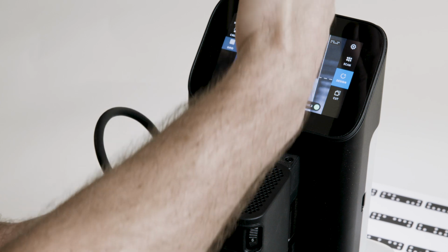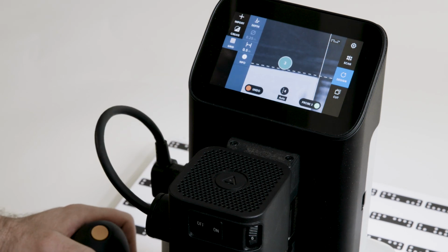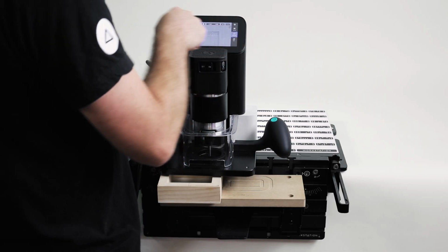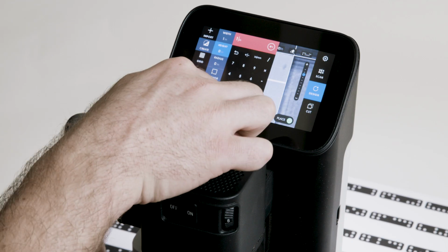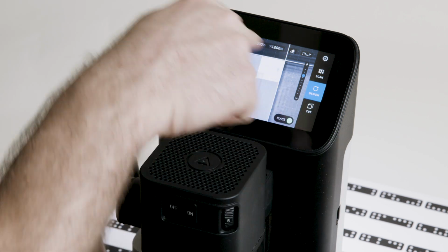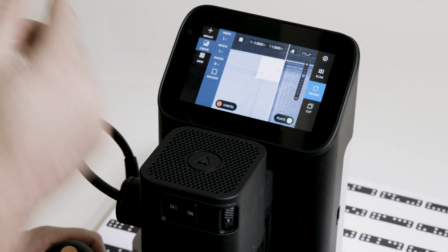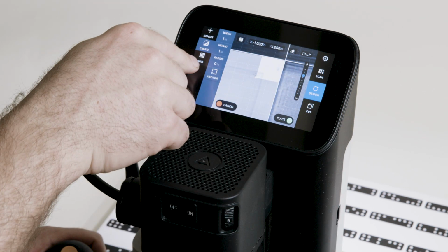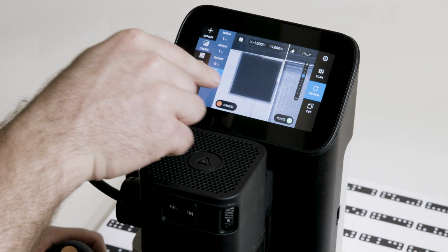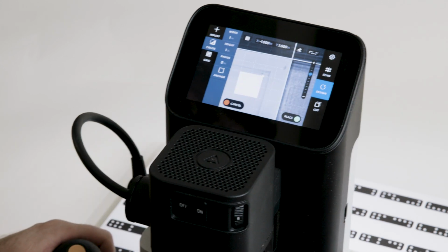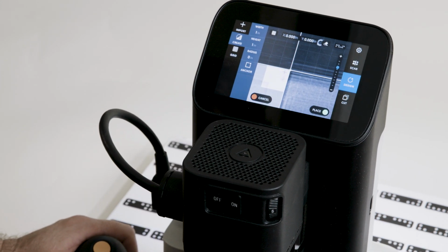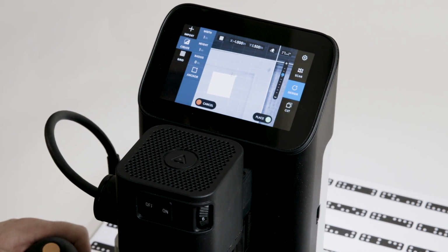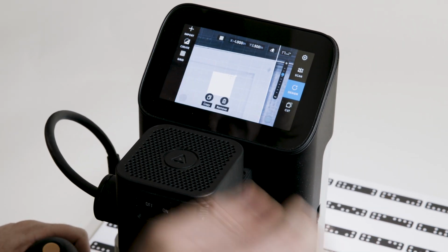So the first axis is technically X, and now I'm defining Y. So they're flipped 90 degrees, but it still enables me to place shapes, as we can see here, at very precise increments, very accurately aligned to the edge of my stock, and also oriented perfectly. I'm going to use the top right anchor point so that I can snap it to 0, 0 and know we're golden. Or snap it to any half-inch increment in this case. Or if I wanted to go in and modify my grid, I can use a different increment.